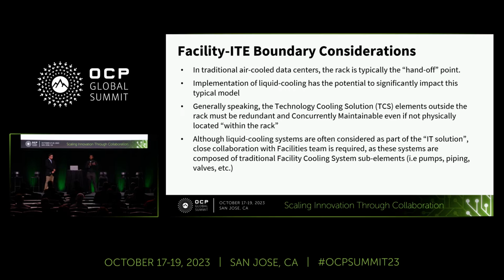So further than that, I would have mentioned that air-cooled data centers are what people would be accustomed to. But as you bring the facility and the rack closer together, or the facility and the chip in some cases, it's no longer just considering the rack to be the handoff point, and you just think about your CRAHs and your CRACs. Now you have to look at all the complexities that are introduced by having a liquid-cooled solution.